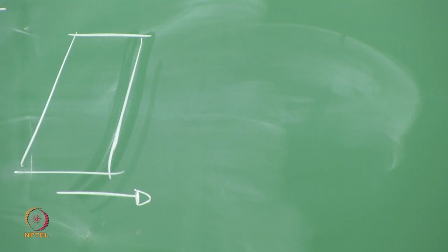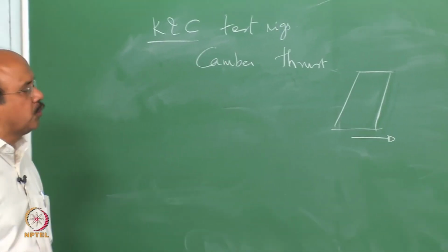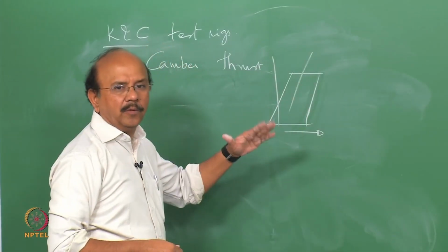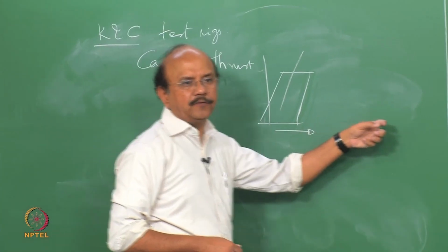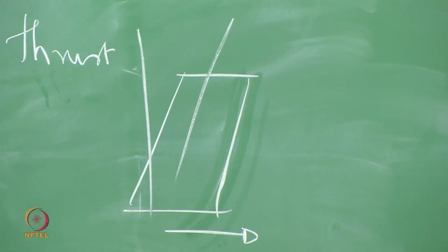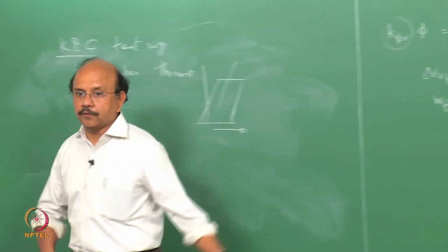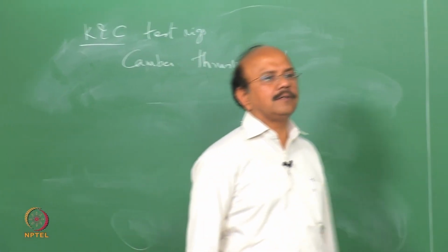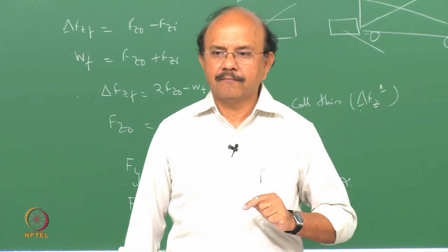Fortunately, in radial tires the camber thrust is very small, so approximate calculations show that about 10 to 15 degrees of camber variation would produce a force equal to that produced by 1 degree of slip angle. So the camber thrust produces a force, and that force is now going to be a force which I have to look at closely.